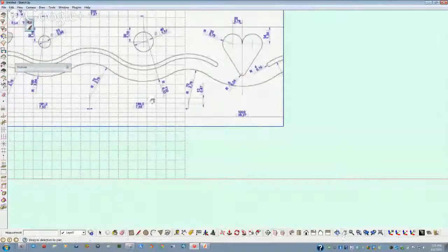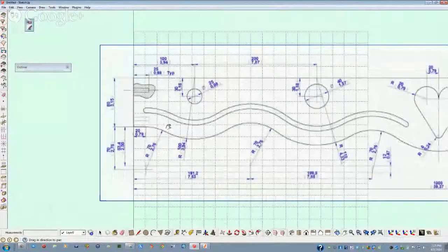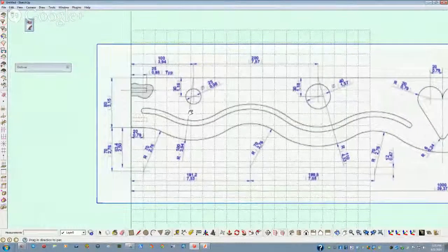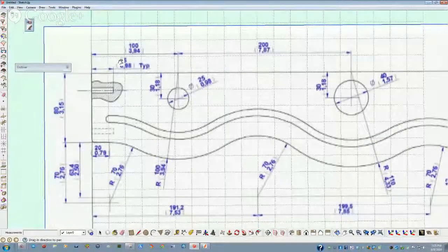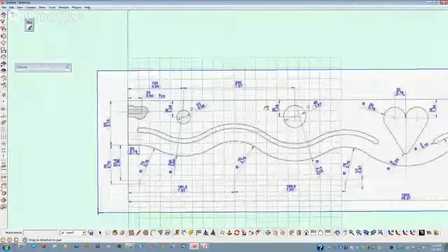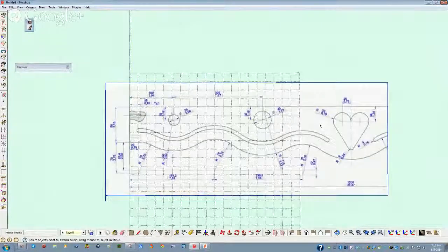And I'll grab the hand down here and pan over. Now you can still see that this hole is way too big yet. In fact, this says it's 25 millimeters, so I have got to resize this so that this line ends up being on here. And you'll see something else which will be kind of a pain, because this is going to grow when I do this change. It's going to change from this corner, so it's going to suck these in. That's just one of the joys.